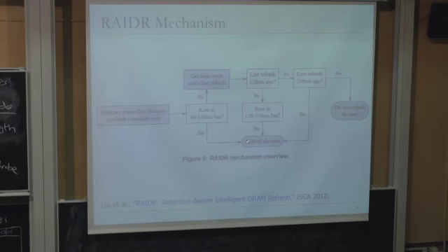If yes, then the row is refreshed. Otherwise, you figure out whether the row is in the other bin, and if that bin needs to be refreshed at this point, then the row is refreshed again. Right. So that's how the controller operates. I will not go into this detail, but maybe we can actually put up the paper so that people can read if they're interested.